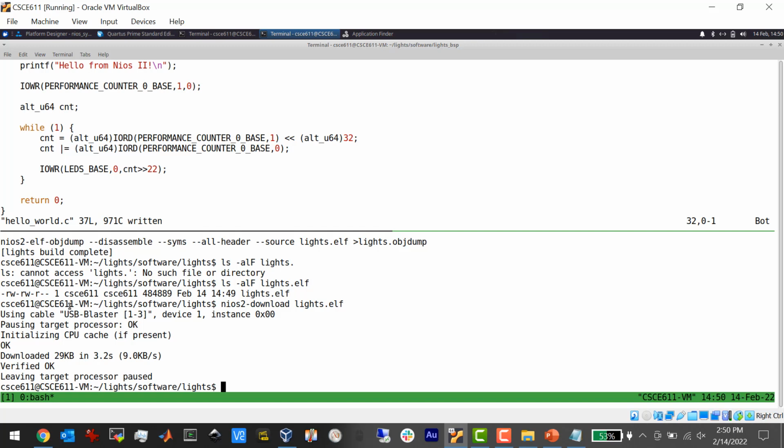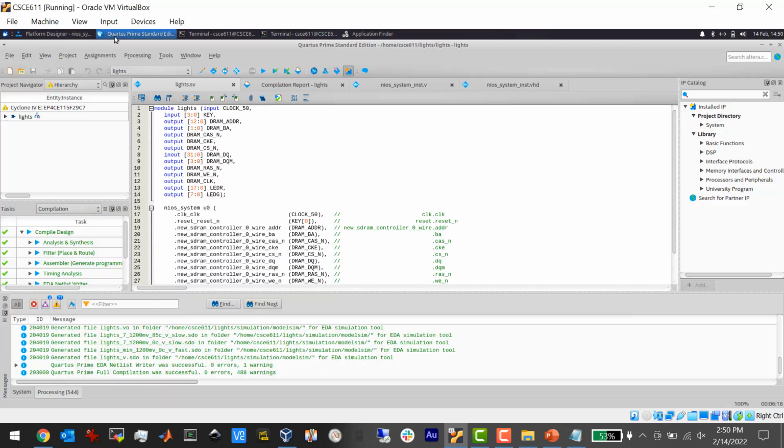Yes? Just for our FPGA, the red does not work when we did that with ours, but we haven't really looked at it since then. Okay, there's a few things you want to double check then, because there's several things that could cause that. One thing is in Quartus, you have to have an output for LED-R on your top level design. You also have to actually connect to it internally inside your design.